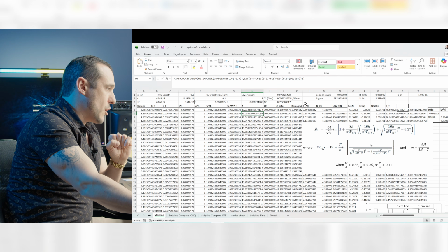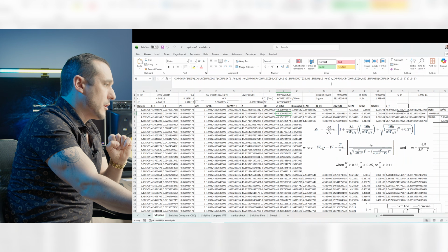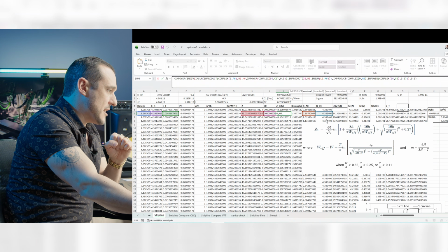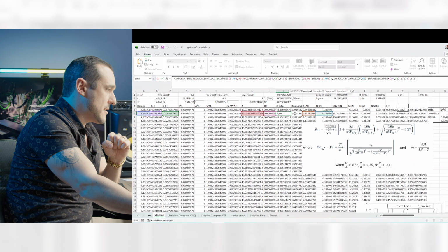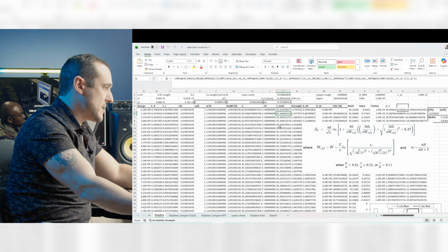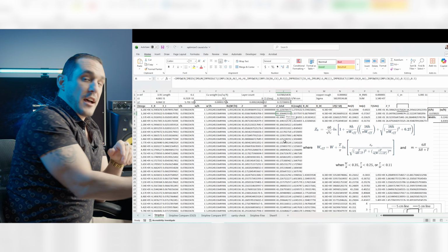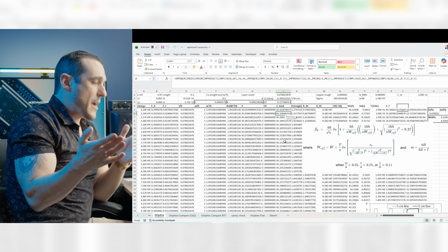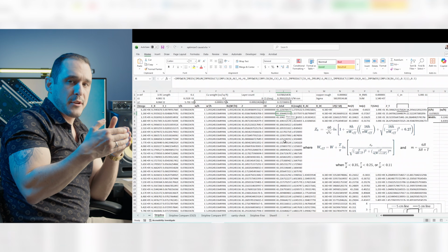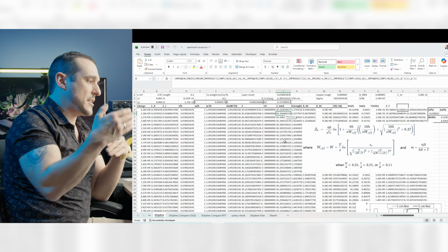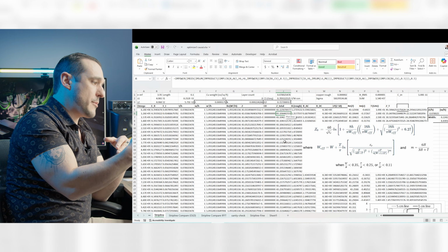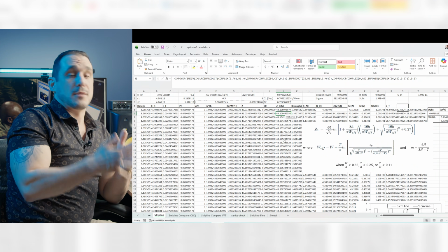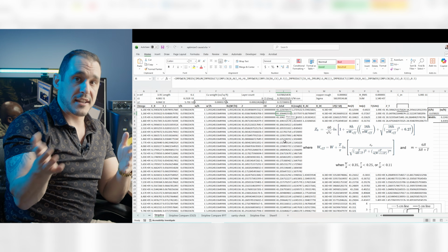Then, once we add in all of the other terms, we then get to our lossy impedance, as you can see right here. We then add in the skin effect resistance and the roughness, and then that gives us our total impedance. Now the reason I originally built this was so that we can do an optimization procedure where we basically converge to just the right amount of width in order to balance the real part and the imaginary part of the lossy transmission line impedance against some target impedance, which is typically taken as 50 ohms.